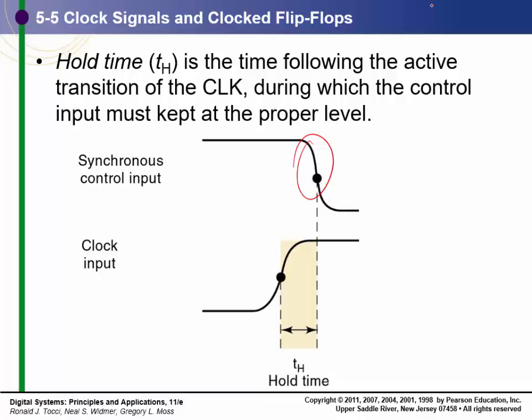So here's our clock edge right here. Our inputs have to be stable this time. Nothing can change during that time. We have a short period before, TS, and a short period afterwards. And that's just part of the design process.